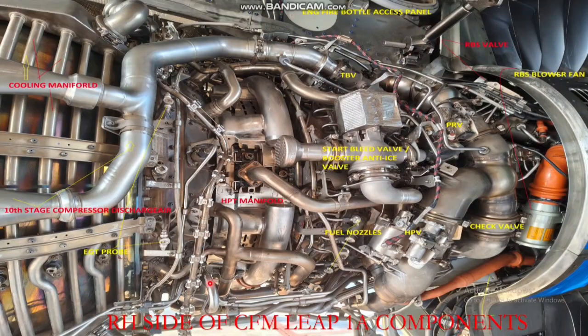If you go to the right side of the core area, we'll just go from the rear. These are all cooling manifolds, as we discussed on the left. This is your 10-stage compressor discharge air. So from here the 10th stage air will discharge through this. EGT probe, already we have covered. Here also you can see 2 EGT probes, and one more you can see on this side. And this is your HPT manifold, a clear view of the HPT manifold.